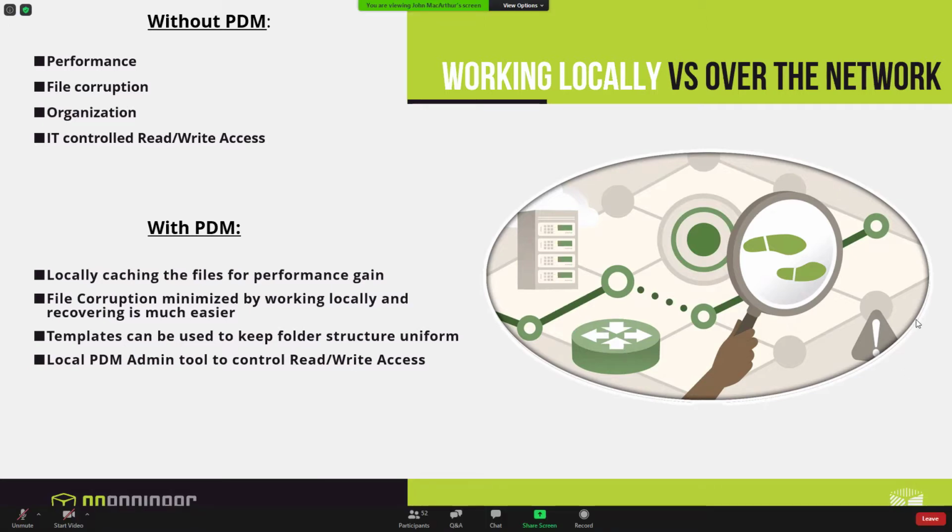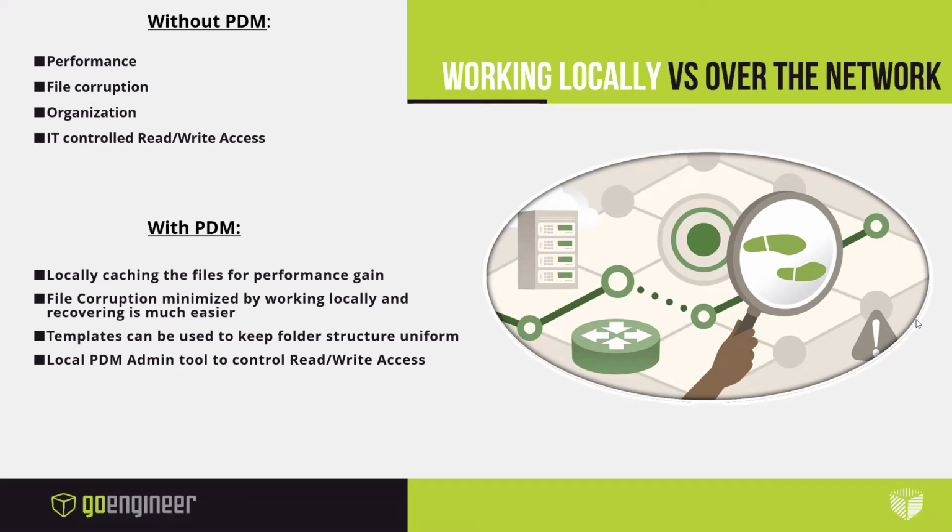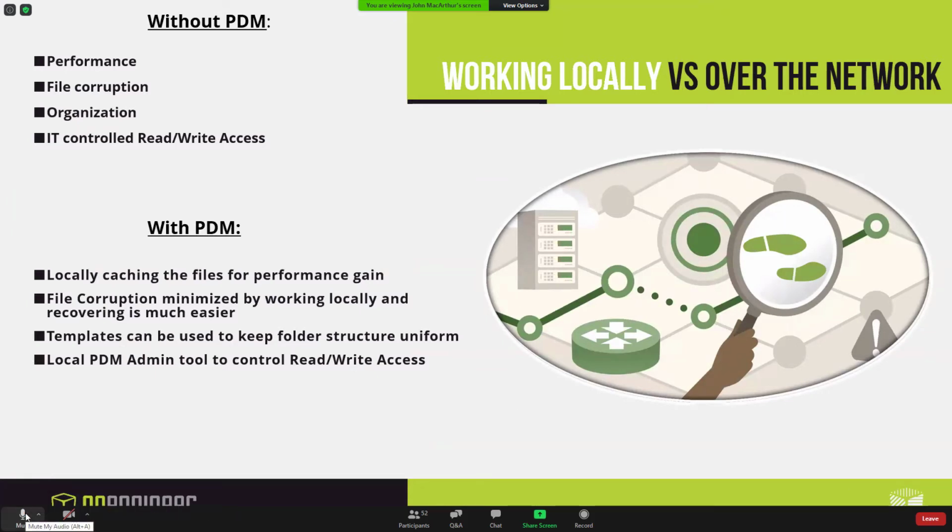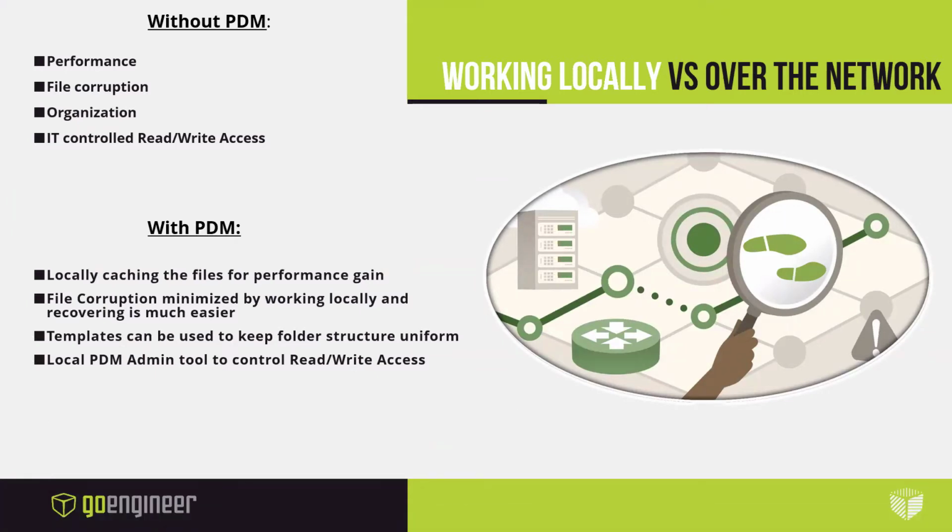The local PDM admin has a PDM administration utility installed on every client, and then password protected admin rights will allow read-write control access. Typically, during an implementation, we train a few PDM administrators at a company, and then they have rights to control the read-write access of folders and workflow permissions within PDM, so that the only thing IT needs to be involved in is backing up the server and updates once a year.